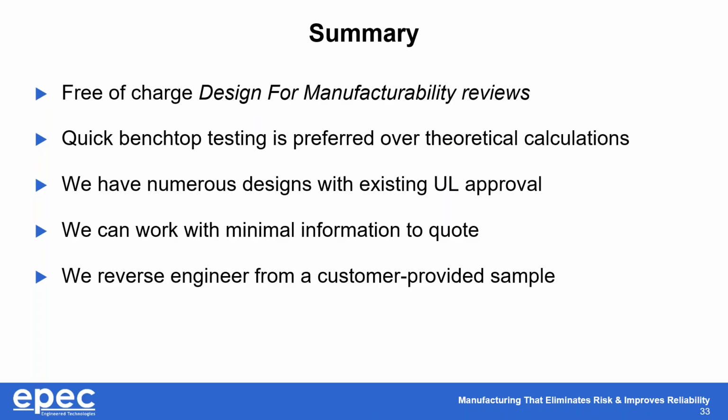We also strongly suggest to do some type of benchtop testing early in the process. And we lean on that more than theoretical calculations that we do to size these heaters. The worst thing that we can do is predict a 35-watt heater performance only to find out we actually need 50 watts because we didn't account for some variable.